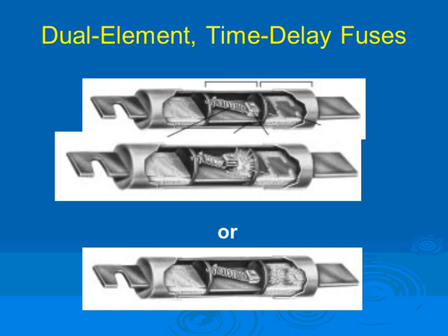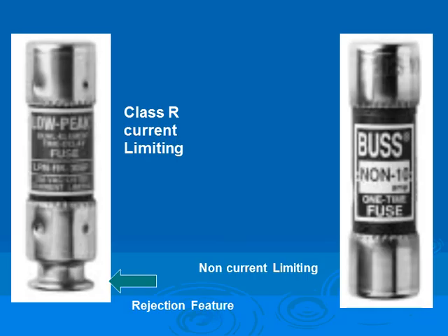So it gives you a smaller size, and remember, every time the fuse is smaller, the arc blast is smaller, and your chances of surviving and going home to your family are higher if you work on this equipment energized. They distinguish between non-current limiting fuses and current limiting fuses, guys.